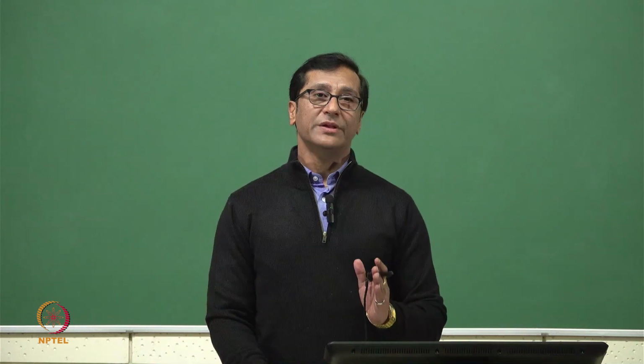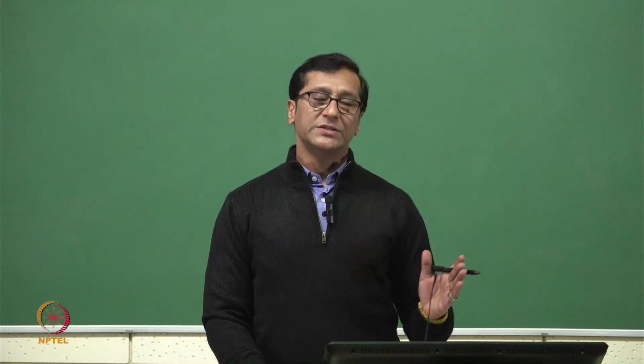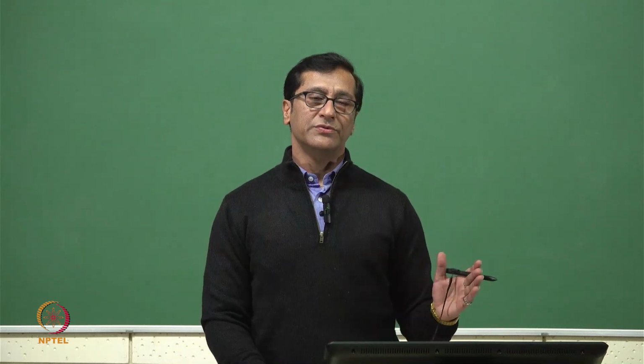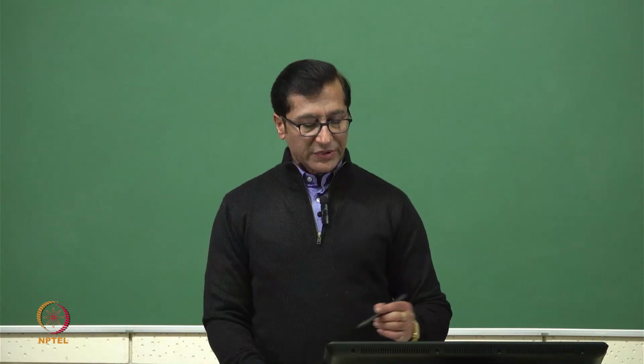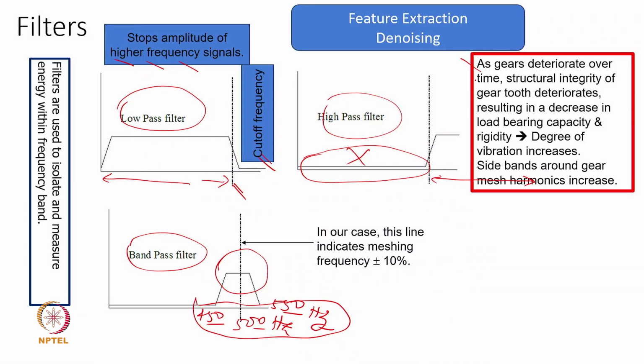If this signal is coming, then only it makes sense to understand, yeah, something is going wrong. Otherwise, noise has so many frequencies, and we can eliminate all those. That's why we say, as a gear deteriorates over time, the structural integrity of the gear deteriorates, resulting in a decrease in load carrying capacity and rigidity. Stiffness also will come down. That will increase the chances of vibration amplitude.